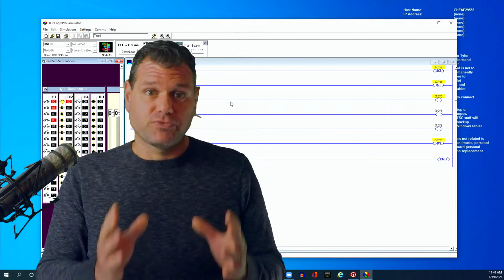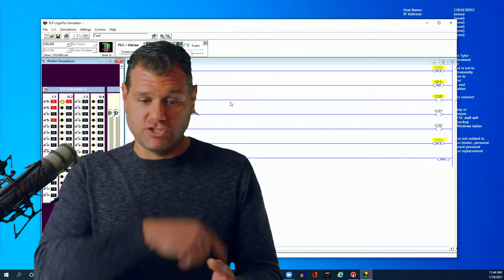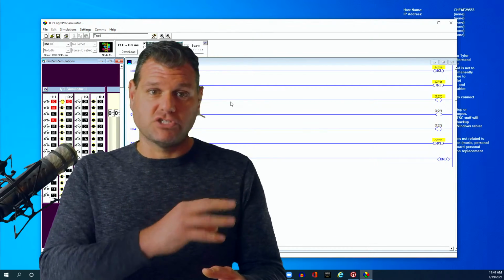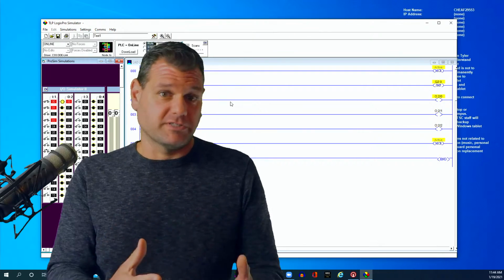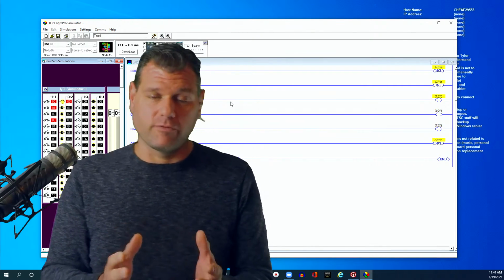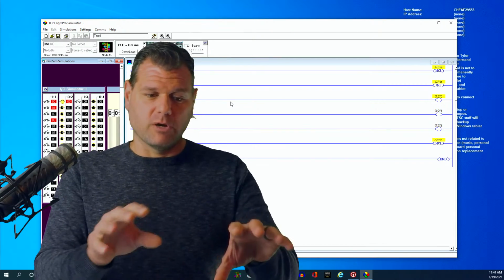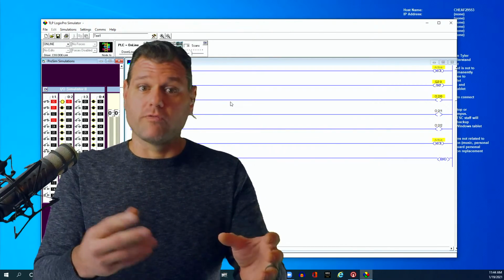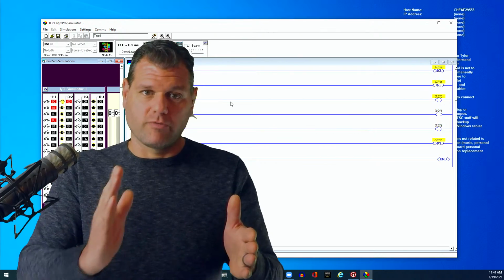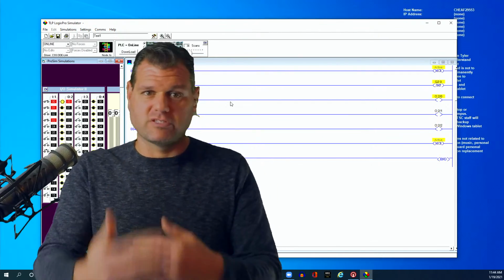The jump leaves it in its last state. So if it was on and it jumps over it and the conditions change somehow, that output stays on, regardless of how the conditions look. So that's something you can be careful with as well, because let's say you're running a motor and the motor has some condition that is for like over temperature, right? If it reaches over temperature, it shuts off, or it reaches the end of its stroke or end of its movement, right?